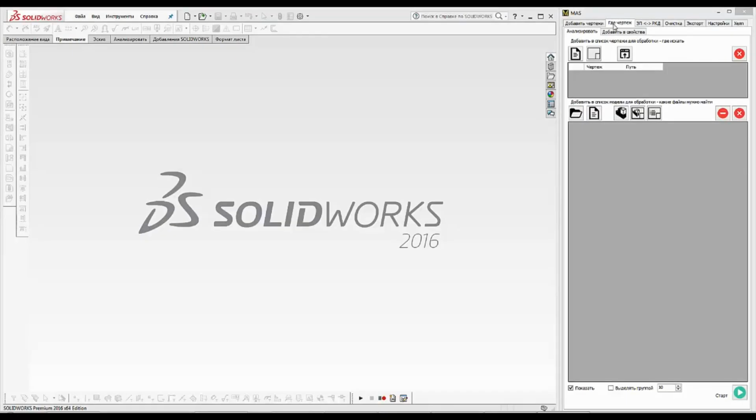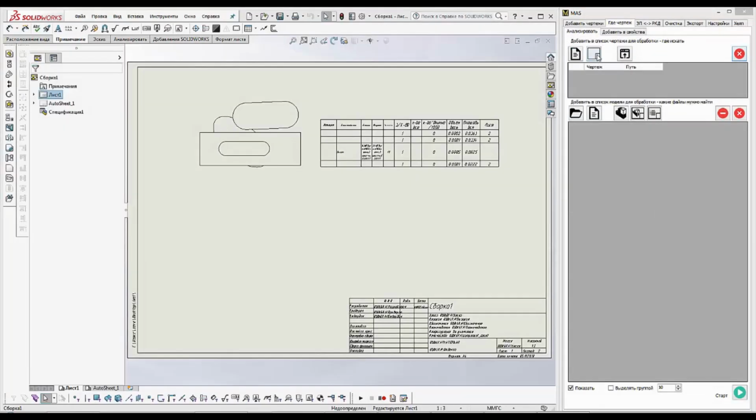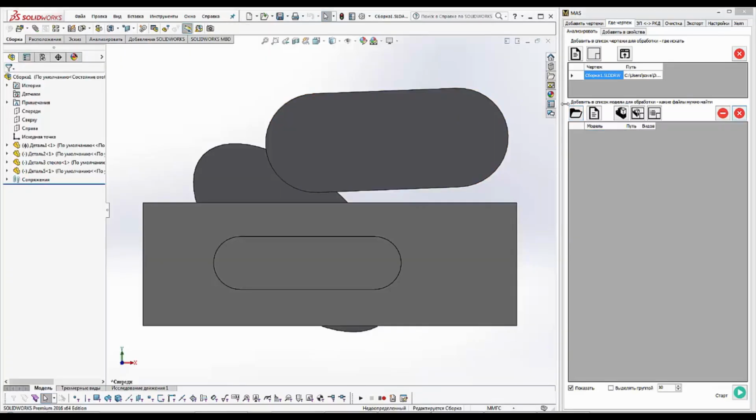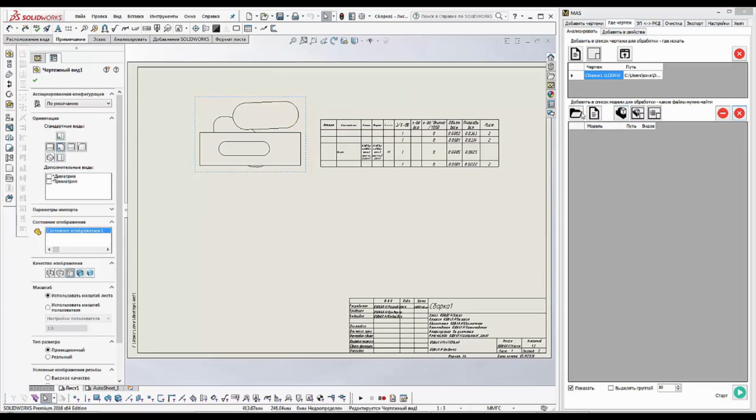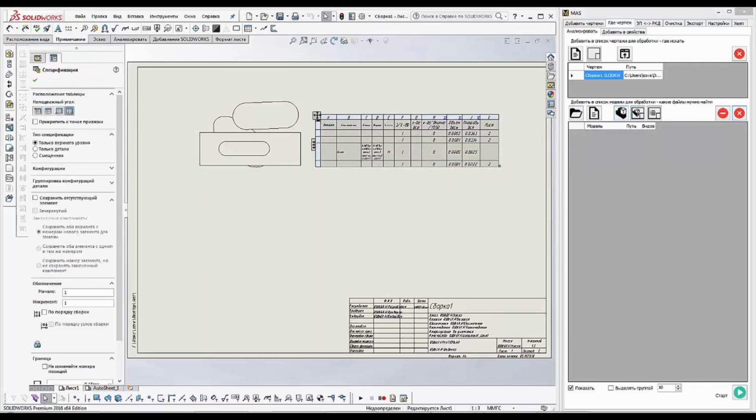Function Find Drawing for Part. This function analyzes drawings to determine where a drawing for a specific part is located. To start, select Drawings to search. You can choose a file or an active drawing. Next, add a list of parts to find. Parts can be added from files, an active assembly model, an active drawing view, or some selected bill of materials.